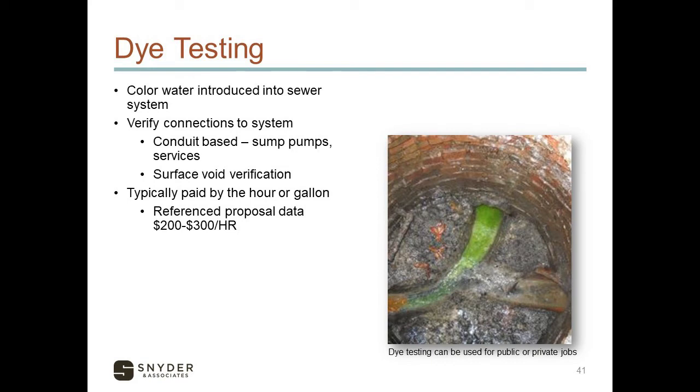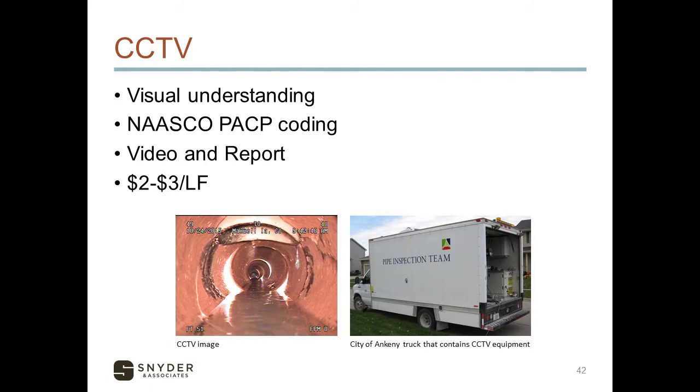So just a little bit of caution. If you're thinking about using dye testing to identify a surface defect, I would probably lean towards a smoke test first. Some of the reference data from recent proposals, $200 to $300 an hour for dye testing to get someone out there into someone's house and just try to identify that source.